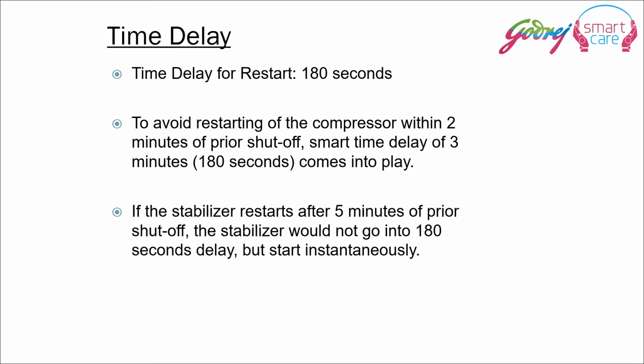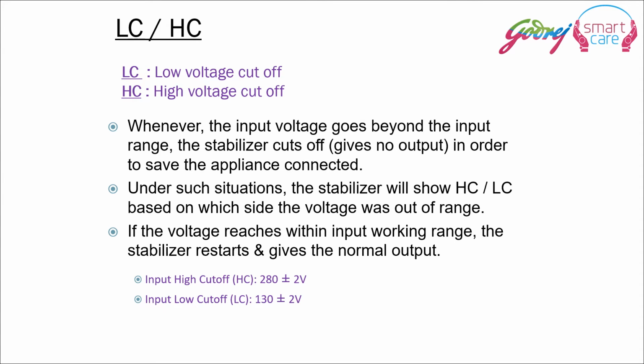And if the stabilizer stops or starts within those 3 minutes, it will start only after 3 minutes, even if the voltage has come back to normal. But if the voltage comes back to normal after 5 minutes, then the stabilizer would automatically start.